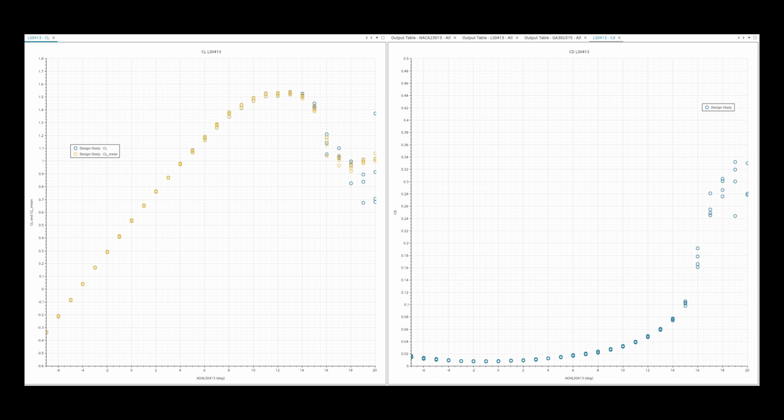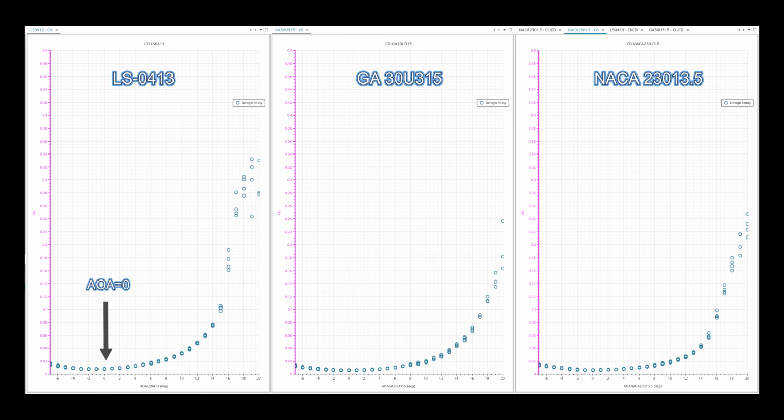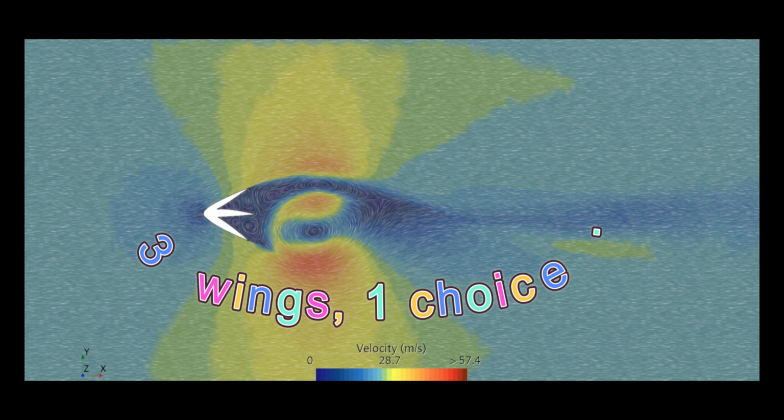1. Let's start with the most straightforward parameters, the lift coefficient, CL, and drag coefficient, CD. For assessing stability, the CD results remain consistently steady, reaching a minimum around zero angle of attack and forming an overall flat parabolic trend. As for CL, I used the same averaging method as in the previous video and compared results across all speeds.